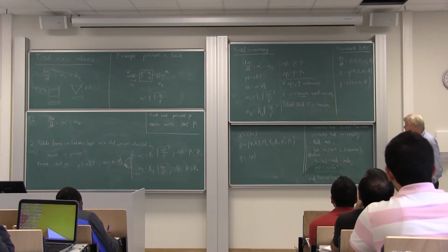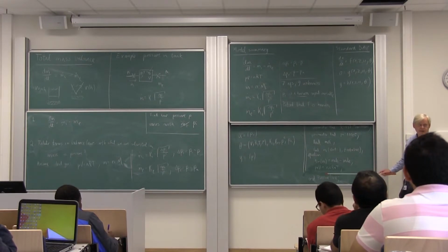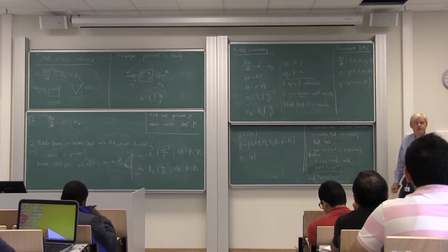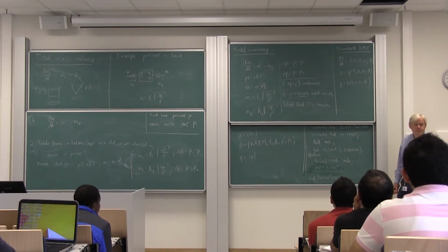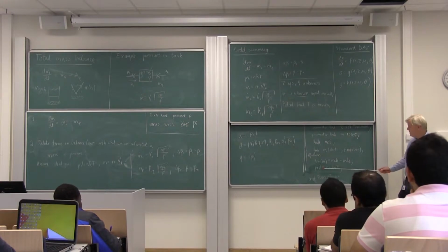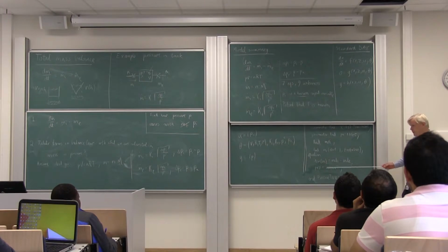And when you run OpenModelica, it will sort your equations. And then without you noticing it, it will move things to the right side and convert equality to what is known in computer science as assignments. That is used, for example, in C and MATLAB and Python and so on. In those languages, this symbol does not mean equality. It means assignment. It has a different meaning. But in Modelica, it means equation.